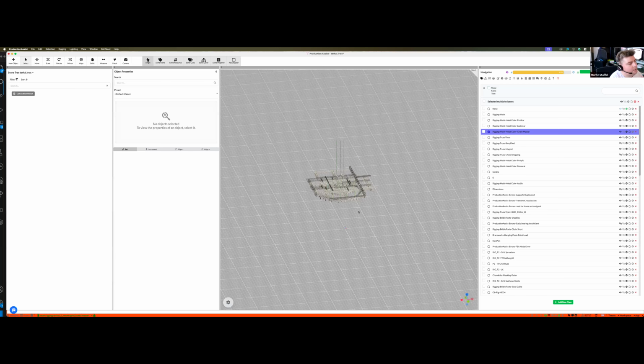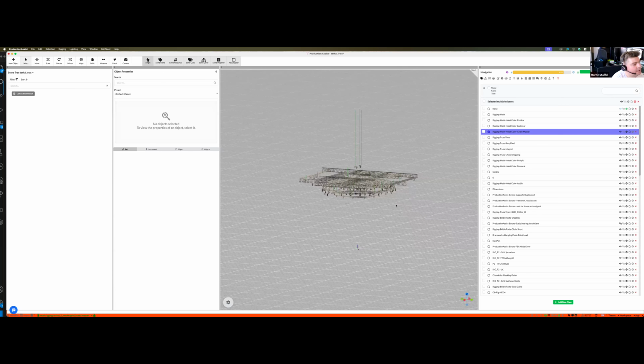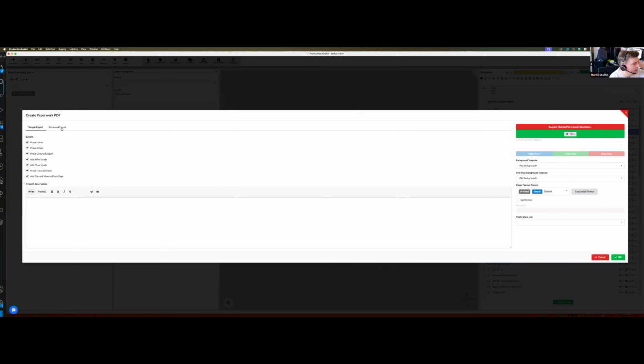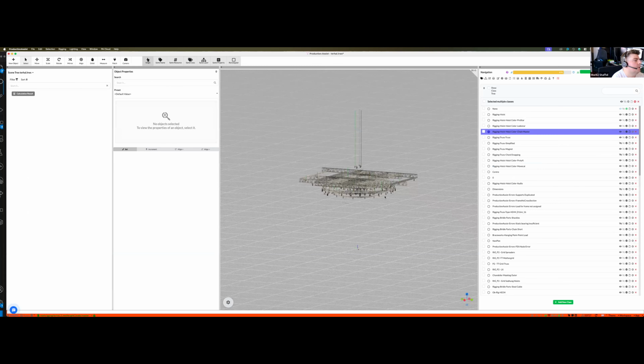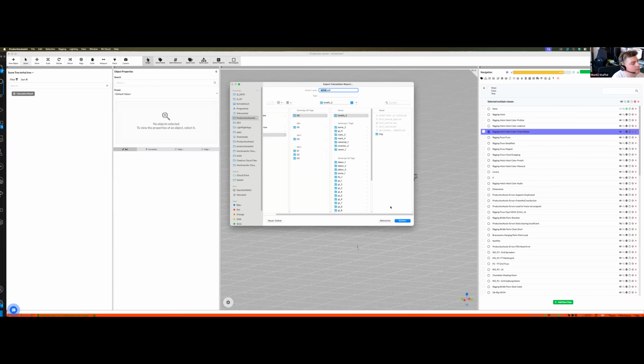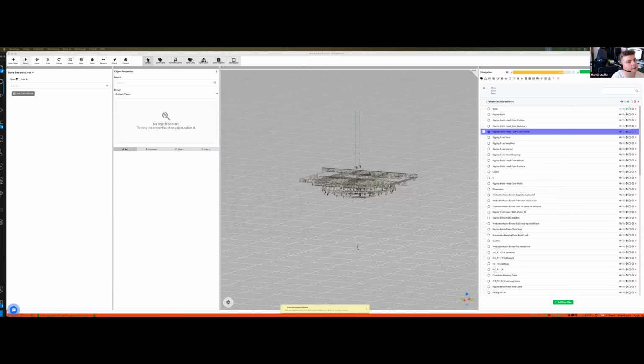A new thing that we've added, and now we jump a little bit more into documentation in here, is a new feature to automatically create PDFs for menu reports. So if I click on File, and if I click on Create Calculation Report, and click on that once report, and let me delete everything in here, I can click on Load, and the new entry is Load Overview for menu. If I'm putting this in here, it adds me the placeholder with this, and then I can click OK. And when I'm doing this, it actually allows me to create a PDF that I can use.